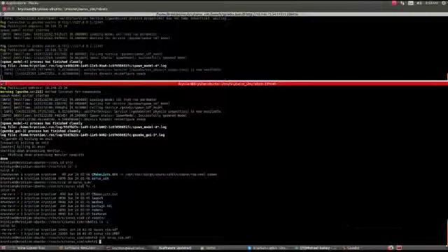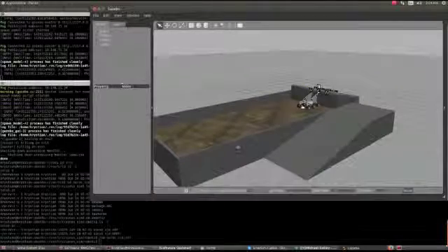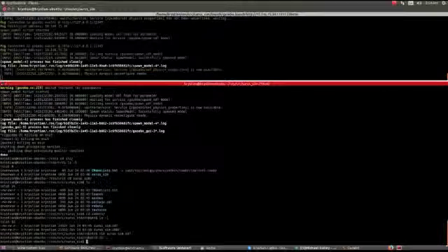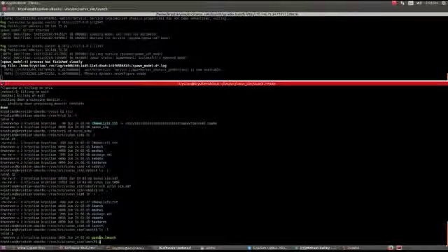So now, if you see here, we're not on the ground anymore. We are in the Luna Arena. The way this is loaded is if you go into the launch file here, you'll see the include file for the Gazebo ROS launch file for a simple empty world. One of the arguments is a world name, which means you pass a value to a .world file that you have created, and what we're doing here is passing the world file for the Luna Arena itself. This is the way you can load a world that you have saved in Gazebo, and go off of that in your launch file.